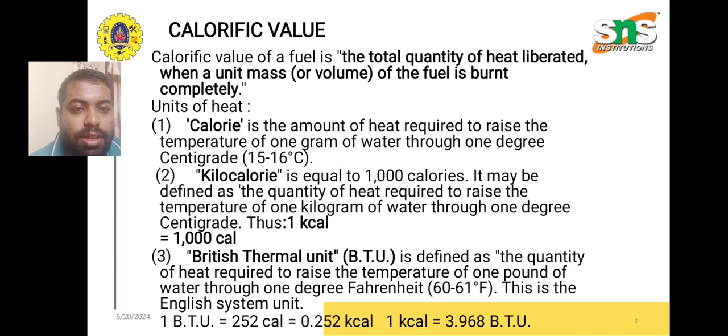BTU, which is British thermal unit. It is defined as the quantity of heat required to raise the temperature of 1 pound of water through 1 degree Fahrenheit, which is 60 to 61 degrees Fahrenheit. This is the English system unit. 1 BTU is equal to 252 calories, which is 0.252 kilocalories, and 1 kilocalorie is equal to 3.968 BTU.